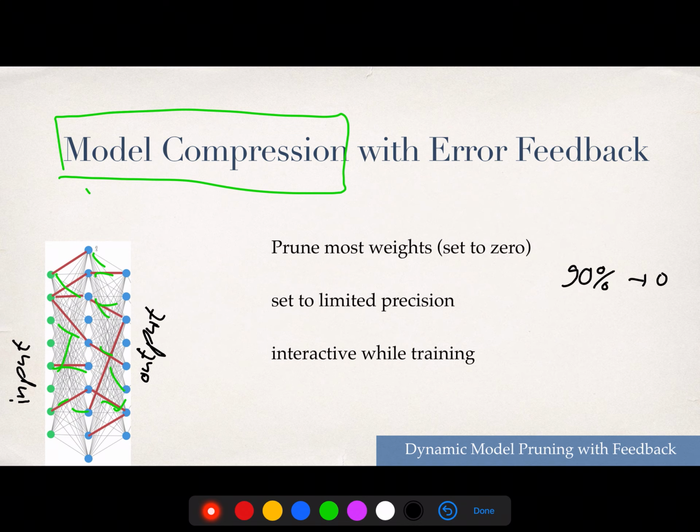So matrix vector multiplications can be fast if you have many cores, right? You can easily benefit from single instruction multiple data. You can benefit if it's a dense matrix, right? But if it's a sparse matrix like now, then it's a bit harder to get easy speed up, for example, on a GPU. But if you have a more flexible chip which supports sparse operations, then you can get even a compute speed up.